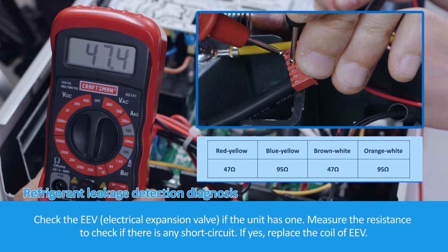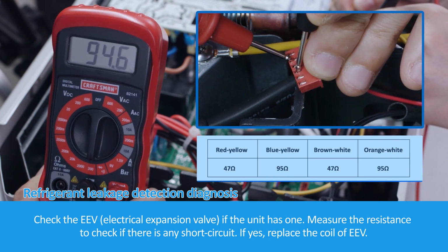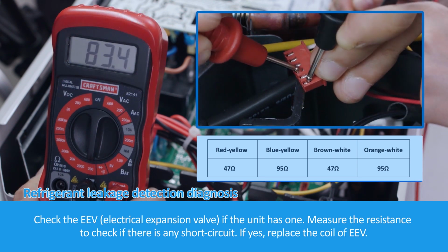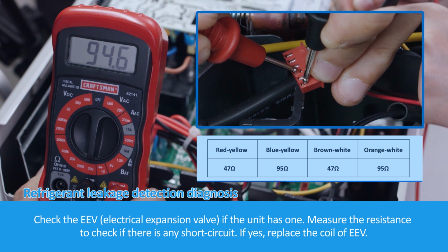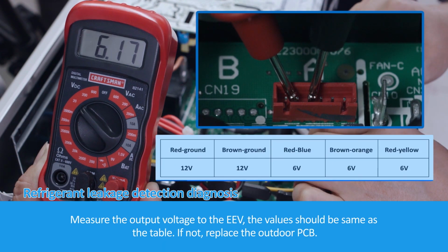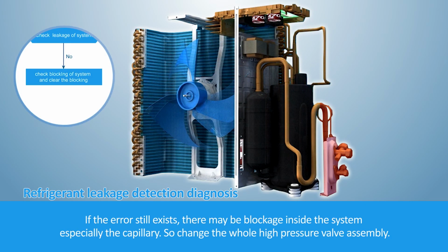Check the EEV, electronic expansion valve. If the unit has one, measure the resistance to check if there is any short circuit. If yes, replace the coil of EEV. Measure the output voltage to the EEV. The value should be the same as the table. If not, replace the outdoor PCB. If the error still exists, there may be a blockage inside the system, especially the capillary. So change the whole high-pressure valve assembly.